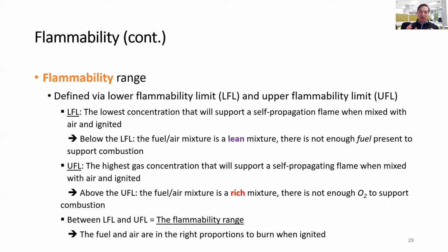If you have a mixture of fuel and air in general, it doesn't have to be hydrogen and air, and the fuel concentration in that mixture is below the lower flammability limit, then that mixture is a lean mixture. At that condition, there's not enough fuel present to support the combustion.